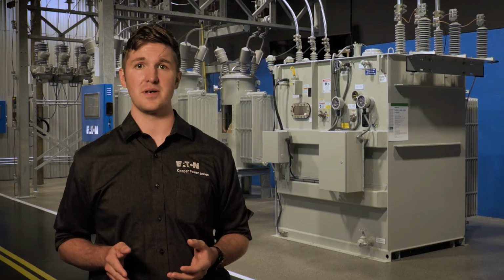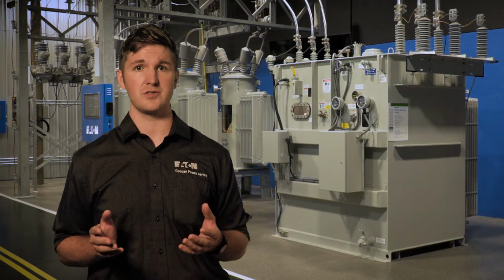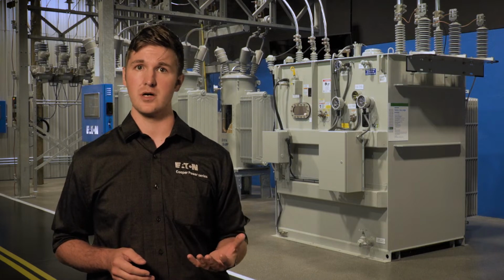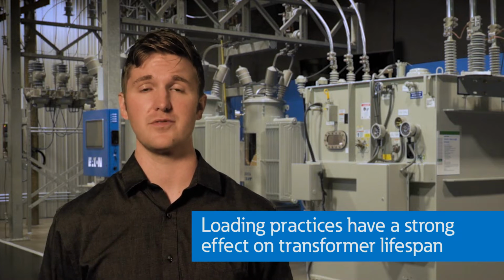The transformer may also be specified with a dual rating at 55-65, 65-75, or 55-75 degrees C rise, in which case the transformer has an additional self-cooled overload capability. For example, at 100% load, a transformer will have a 55 degrees C rise, and at 112% load, it will be a 65 degrees C rise. The loading practices which you employ have a strong effect on the overall lifespan of the transformer. Understanding the consequences of a transformer overload allows users to size their transformers accordingly and recognize whether a loading practice is promoting efficient use of the resources or is leading to premature failure of the transformer.